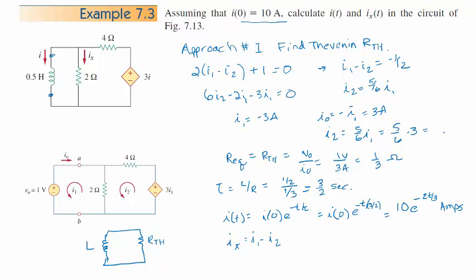So this was 5/2 amp right here, and you have I1, you have I2, and you have the time constant there. Then it's just a matter of substituting the values in. It'll have the same LR time constant though. Everywhere in the circuit we're going to have that same LR time constant because that is the natural response of the circuit. So that would complete that problem.